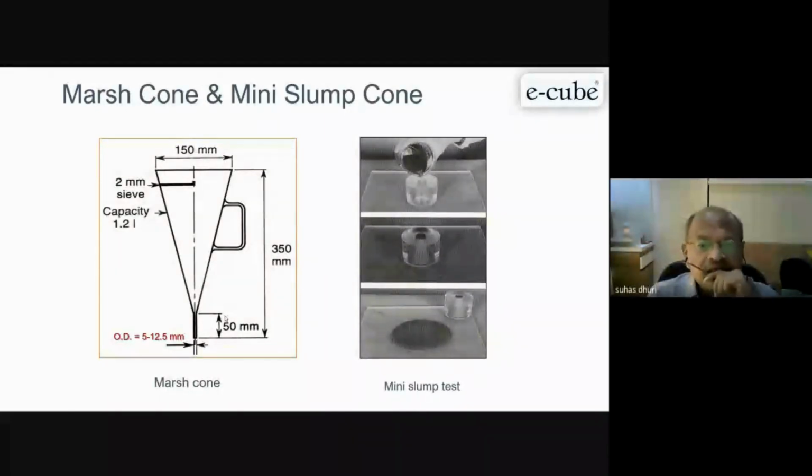Cement may have similar properties as per the IS standards. IS 269, whatever is there, it is meeting the requirement. But there is a huge range in between, and some of the minor components play a major role in the compatibility of admixture to the particular type of cement. So one has to remember, when you are using OPC, and suppose you use PPC, the same admixture may or may not work. Suppose you use PSC, Portland slag cement, the behavior will be different for the same admixture.